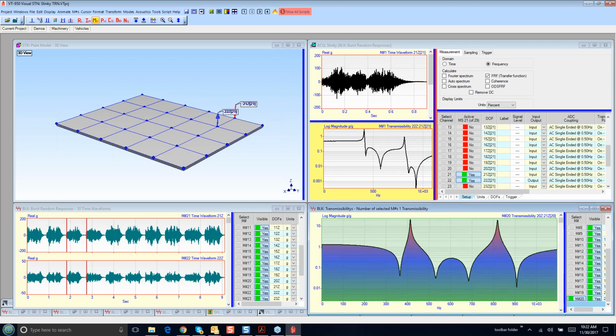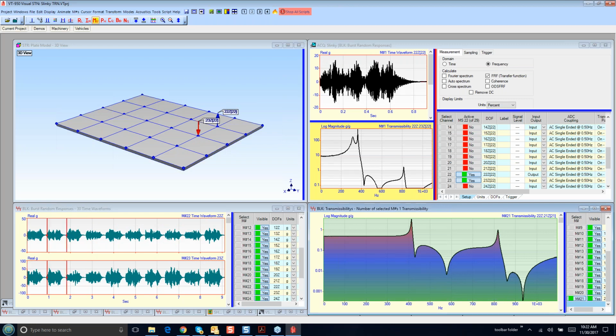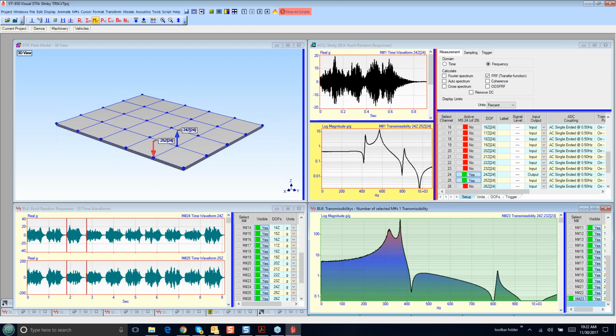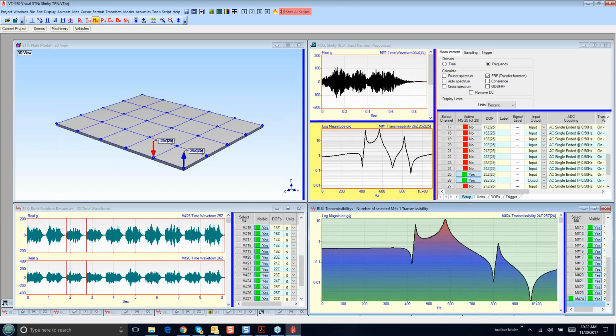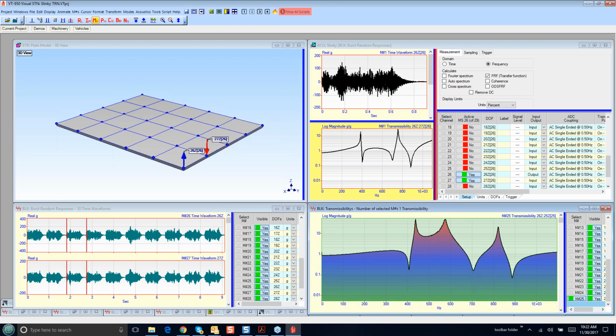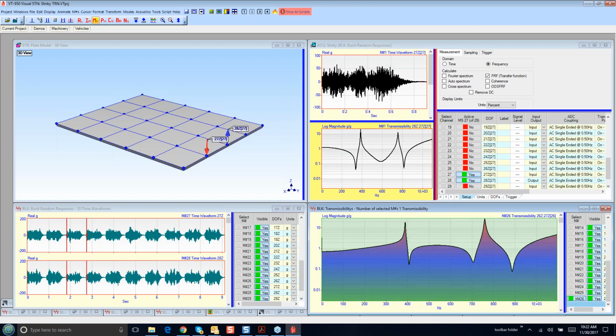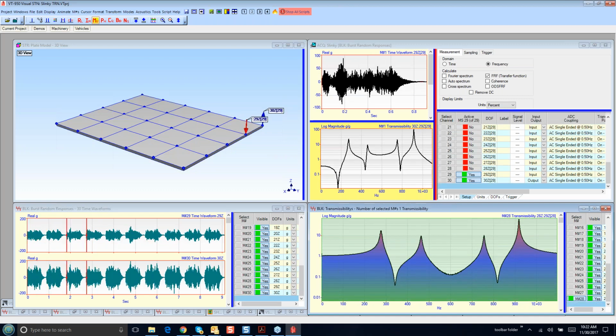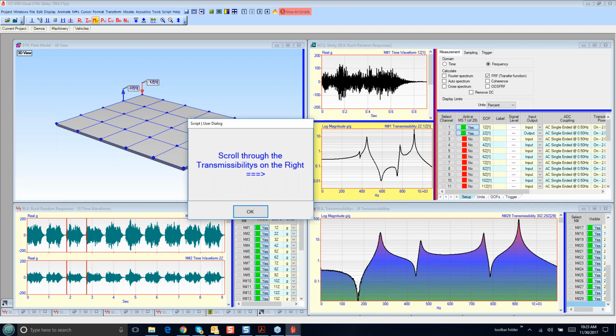And a car running around a track, we can't measure the forces, they're distributed. And the only thing that's required here with these transmissibilities is that the force is applied at the same point, same direction. We can't measure it. We call that steady state. Modes are only defined for a steady state system where the forces are being applied at the same point in the same directions. A car running, there's all sorts of forces from the motor and the ground and so forth. So there's a lot of inputs, but the levels can go up and down